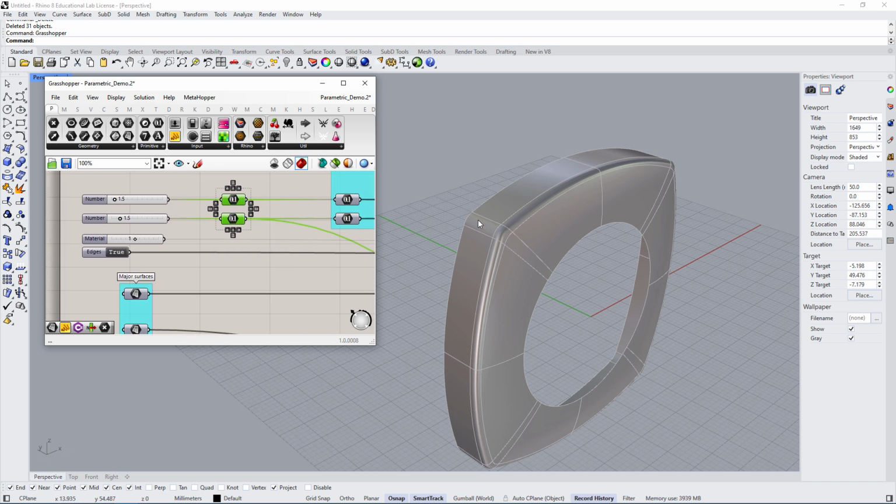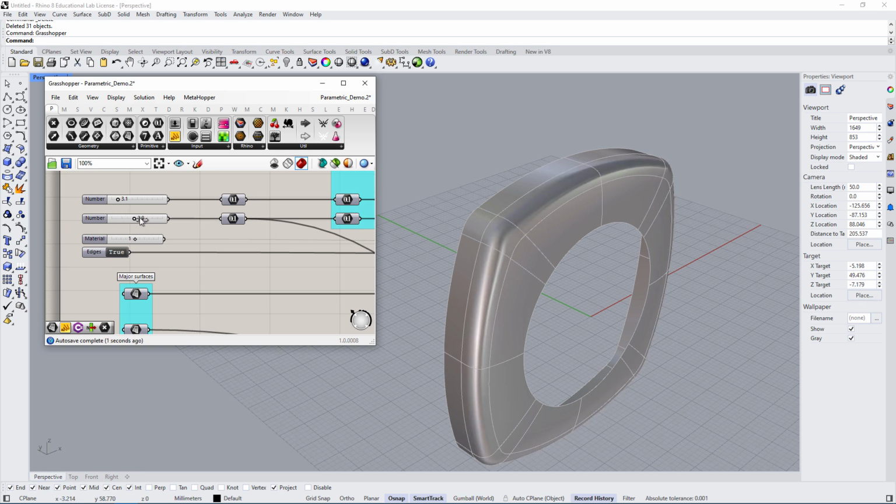So here you have something that looks very similar. You have a fillet edge that has been defined with this constraint. And the constraint, we call that a variable. The variable is set to 1.5, but you can change it. That's why it's called a variable, right? It can vary. You can change what it is. And now you can see it's updating. It's becoming larger. We can make it smaller. And we can change this fillet independently of the other one.